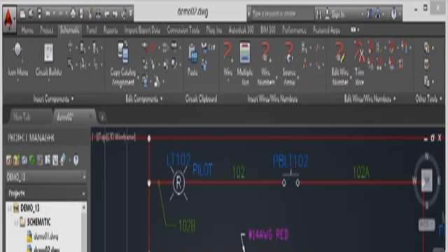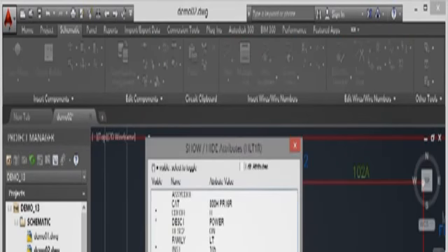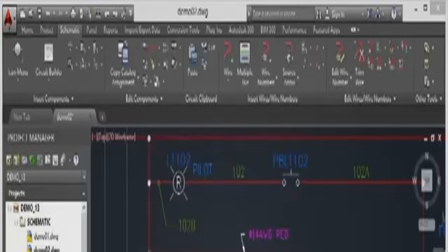It's very easy. I select the component again, right click, and I go to Attributes. This time I go to List Edit. There they are there, and you can see, look, there's description 2, and there's the on there. And at the moment, the little asterisk that prompts it to be visible isn't there. It says Select to toggle. So if I click there, can you see the little asterisk comes back? I click on OK, and that switches it back on. It's that quick, simple and easy.